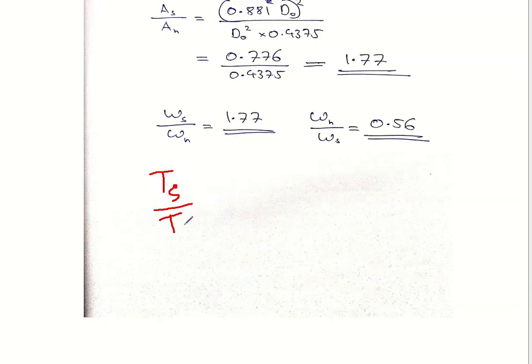Because in our derivation, I had already told you that the T that we find in the torsion equation is actually the resisting torque. It is the resistance offered by the material. It is not the applied torque. But in most of the cases, this will be equal. The resisting torque and applied torque will be equal, so we can take it interchangeably.